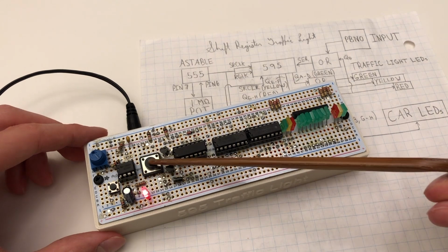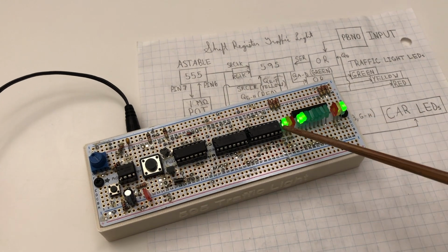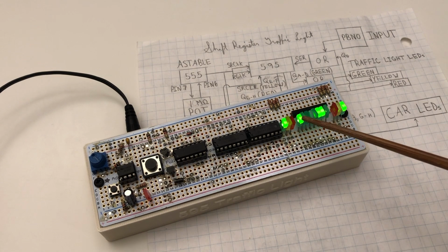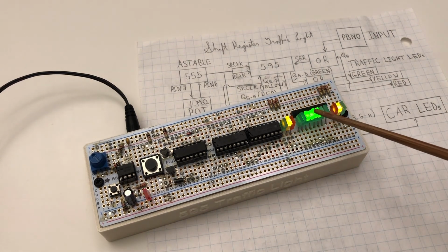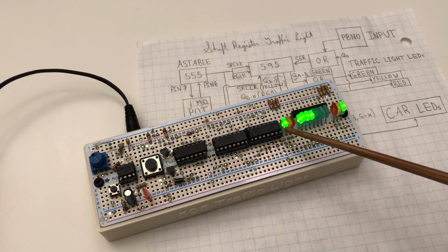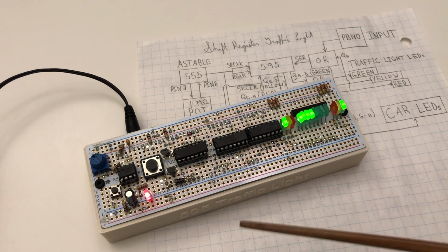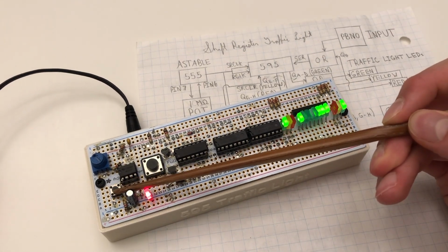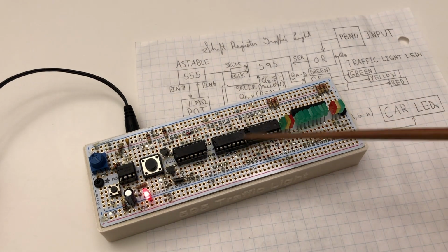So when the button's pressed, the traffic lights begin to cycle through their states, and also these LEDs, which represent the cars, turn on according to the traffic light. So as you can see, these 4 LEDs turned on when the light was green, and as it turns to yellow and red, they just flow out of the intersection. And this is a never-ending loop that will go on forever and ever until you press this reset button, which is connected to the SR clear of both of these shift registers.